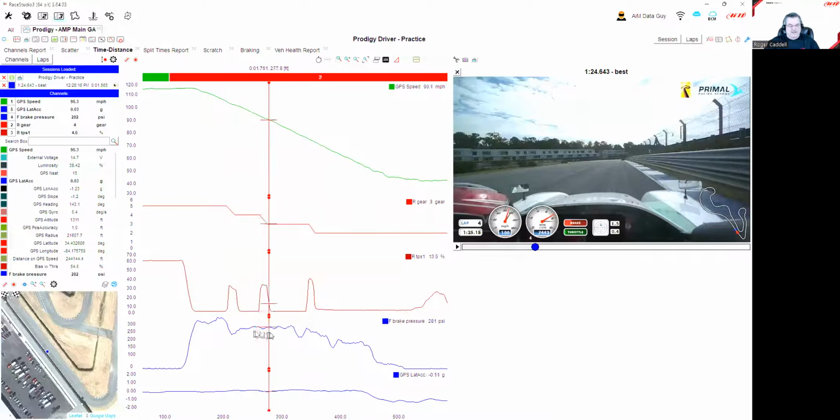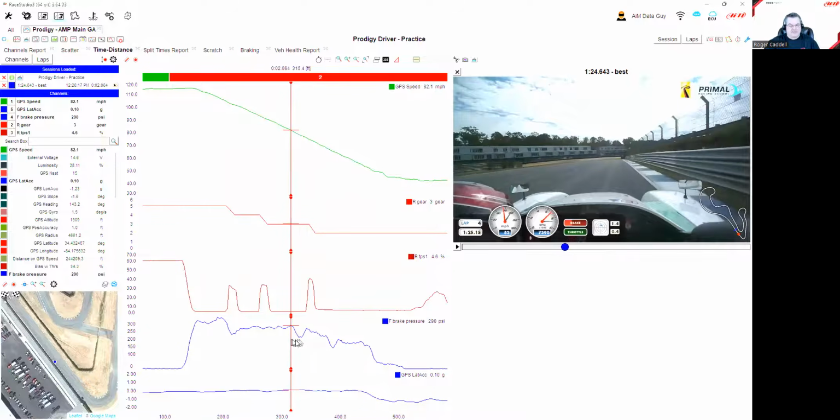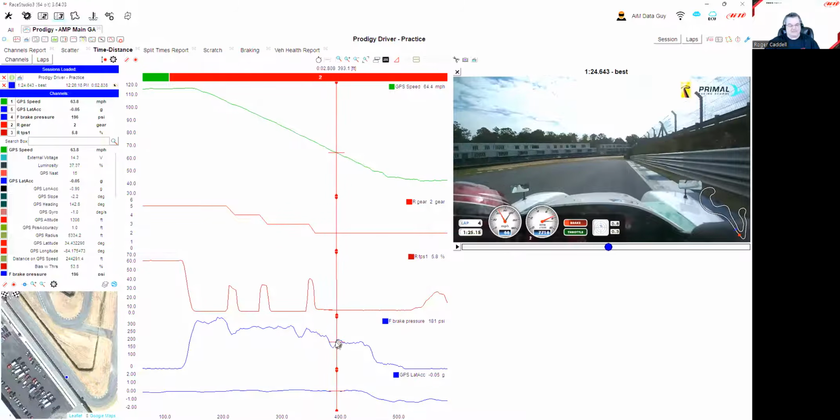The driver did pretty good on the middle downshift, the downshift from 4th to 3rd. I'm not seeing that same problem, but then we see it again a little bit here, the dip in the brake pressure, and we see it again right in here. None of it is terrible. I had to work pretty hard to find things in this data to be able to coach on, because the driver's pretty good. But when you find something, I wanted to share it with you and start to get an understanding of what is going on here. So that's another thing you can look for in your data.